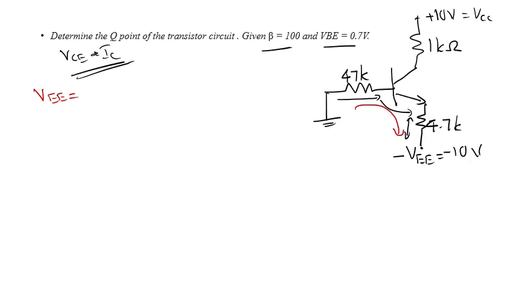So supply voltage is equal to IB RB, plus VBE base emitter voltage, plus the voltage across the emitter resistance, that is IE into RE. So you have to obtain the value of IB or IE from this equation.